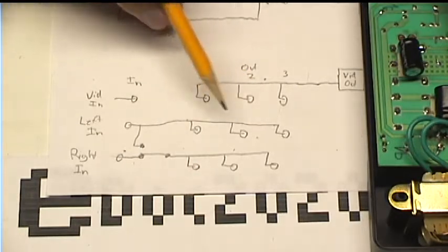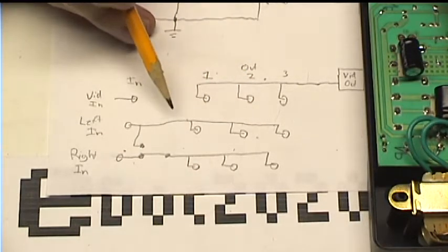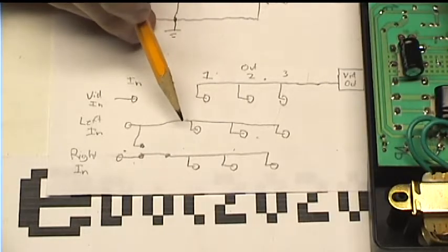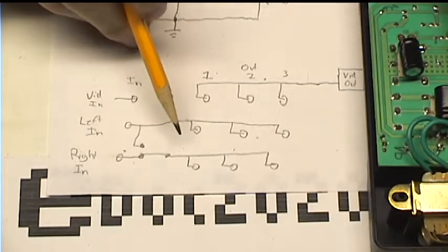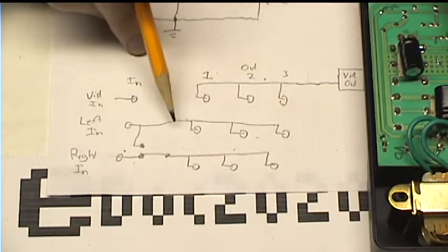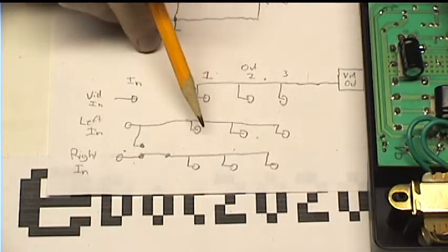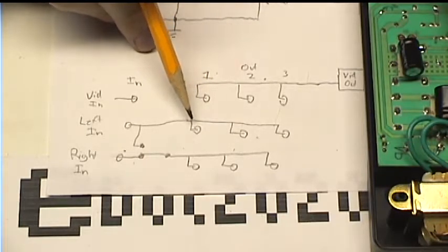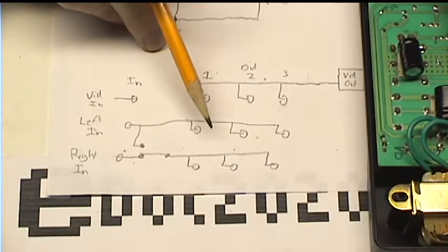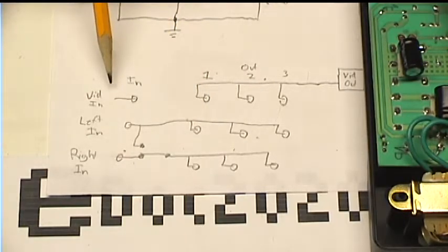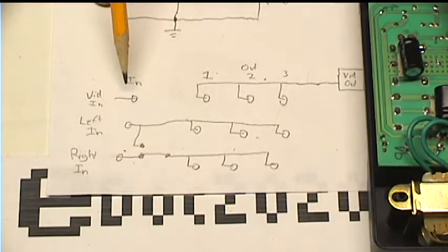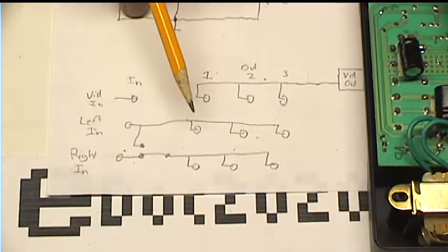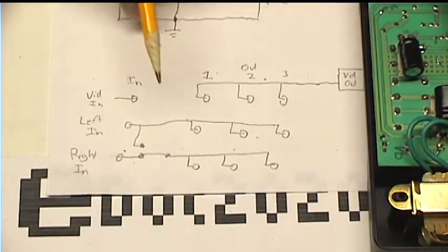If you have three devices connected on the output and each has a 75 ohm resistance, you end up with an equivalent total resistance of 25 ohms, which can drag down the output of your video generating device and lead to a distorted picture if it's not expecting to drive additional loads.